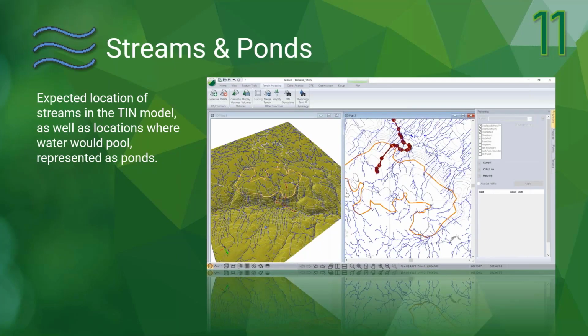Streams and ponds. This one is a really useful tool. Again, redone from version 10, more accurate, substantially faster, and it gives you the expected location of streams in your tin model, as well as locations, of course, where the water would pool, and we represent those as ponds. So this tool is very useful, in particular when you're looking for where to put a road.